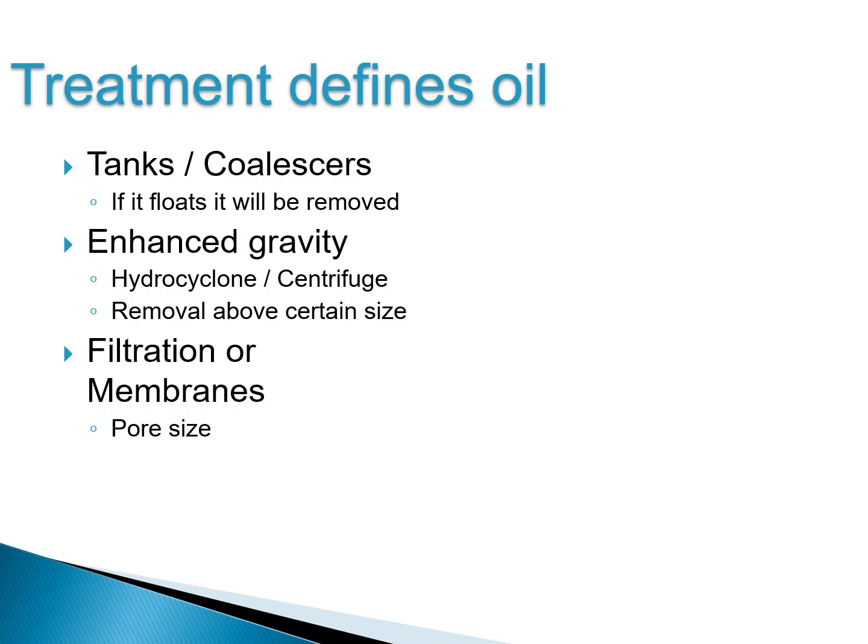There's other technology that I call enhanced gravity separators or enhanced gravity systems, and these are devices that effectively spin the oil in the water at high rate so that the gravity is increased. It might be a 5 or 10 gravity or 10G centrifuge, and then all that does is make those oil and water droplets, the oil droplets, come together a little bit better so they can be separated.